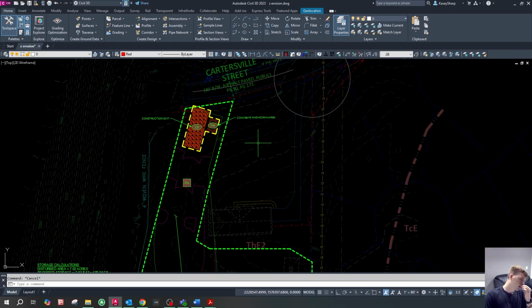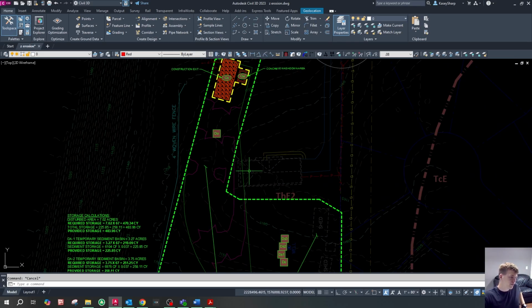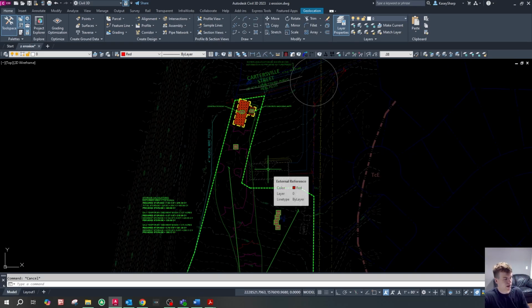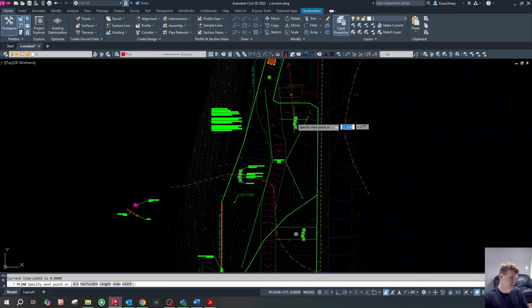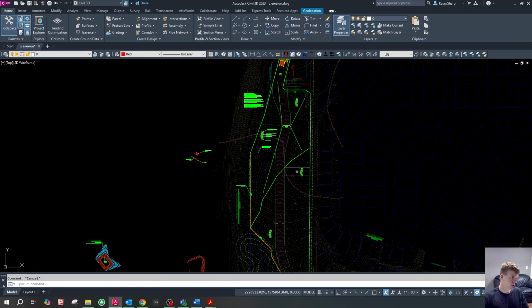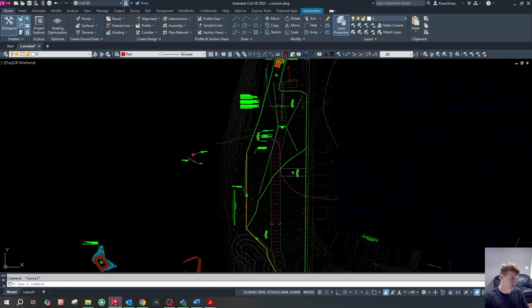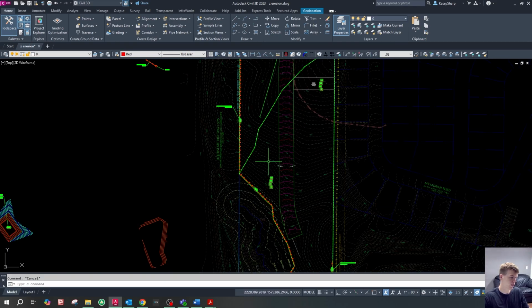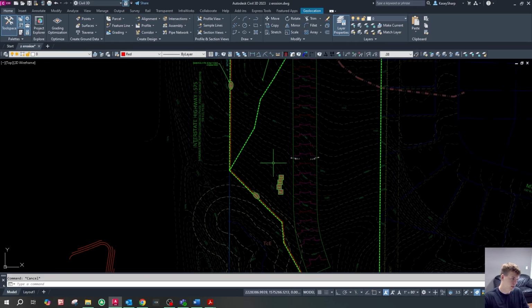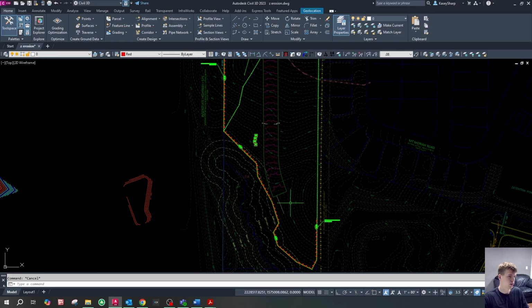So we have a high point here where this house is, and everything in the front yard of the house is draining this way, right? And then everything on the south side of the house, as you can see, it's like one big long slope that's sloping down as we move from front to back of the site, and then it's also sloping from right to left, or kind of from top right, it's sloping down to the bottom left.